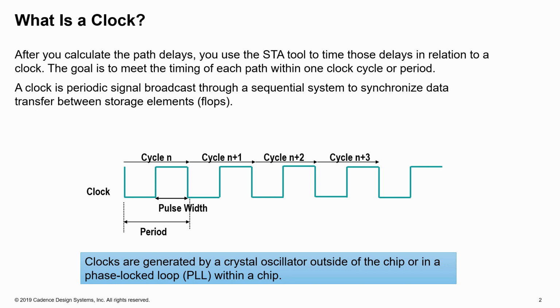In digital circuits, clocks play a vital role because they trigger the storage of these memory devices, and they also control your state machines. So if you have flops or latches in your design, you're using a clock to trigger that storage into those flops and latches. If you think of the Verilog language, anytime you see an always @(posedge clock), always @(negedge clock), or always @(clock), these are the storage devices that you're creating through Verilog.